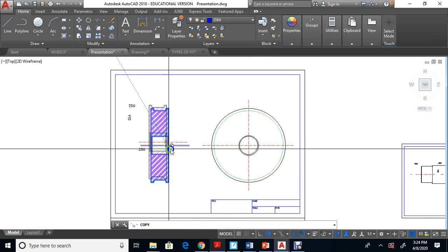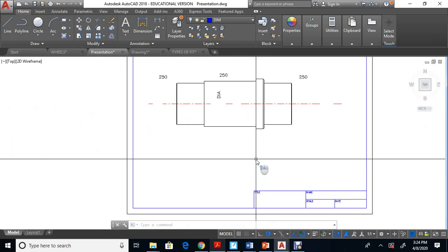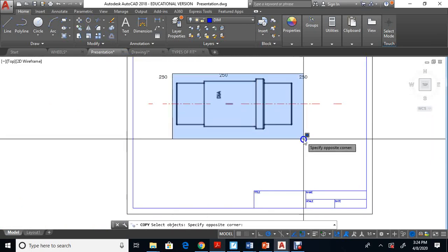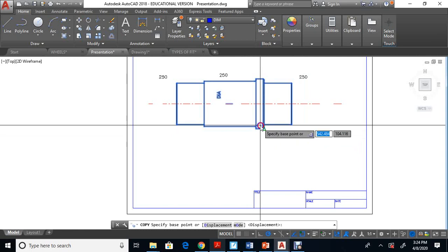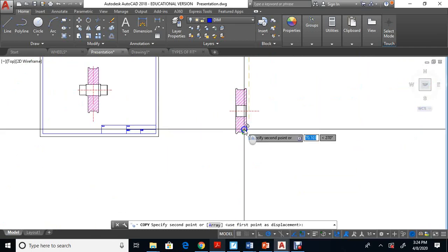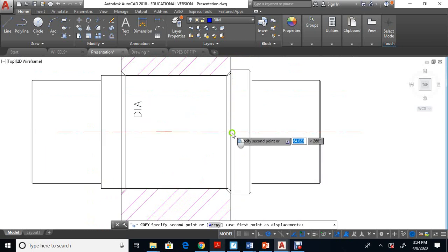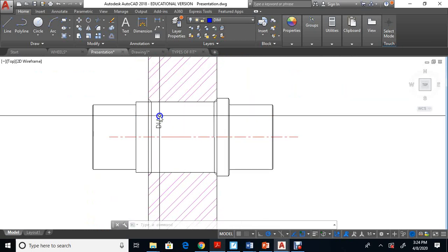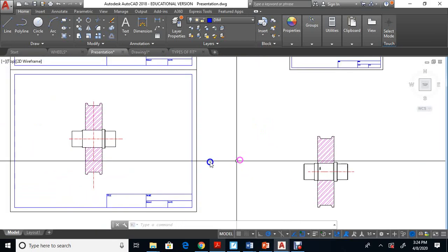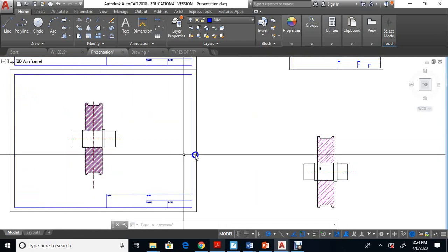And I'll copy the center over here. And then I'll copy the axle without the dimensions. So I'll copy this axle here, and I'll pick right there, and I'm going to put this right in the hole right here, right at the end. So it's going to hit and interfere here. And now I go and clean it up. See, this is what this looks like here. And then I clean it up here, remove some lines, and I make it look like that.